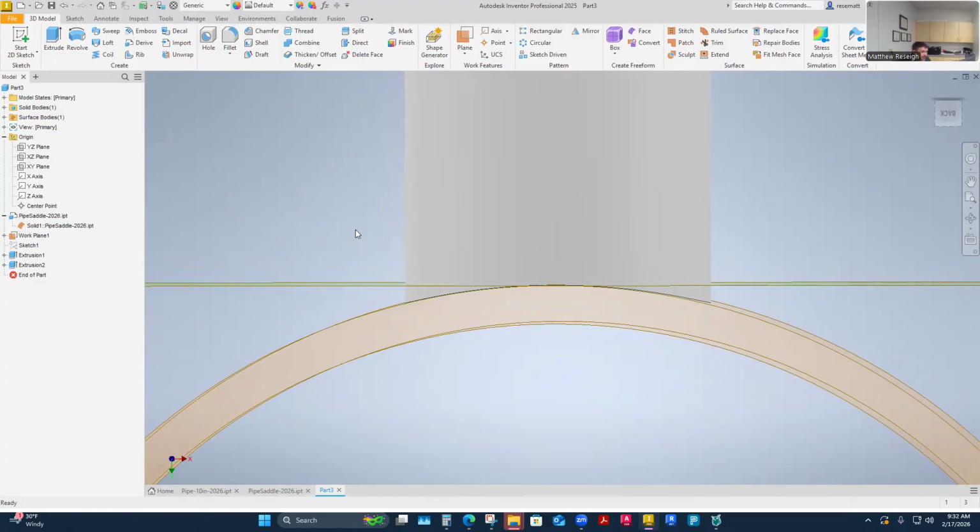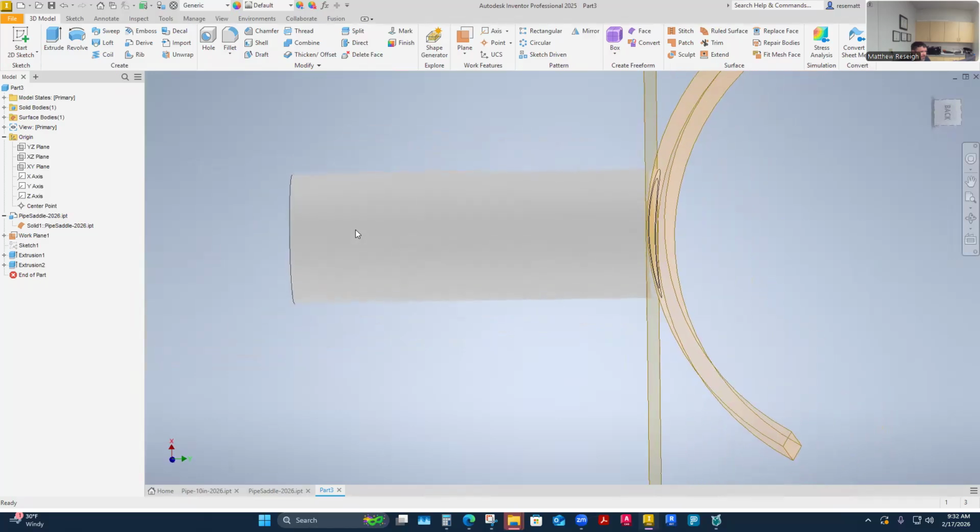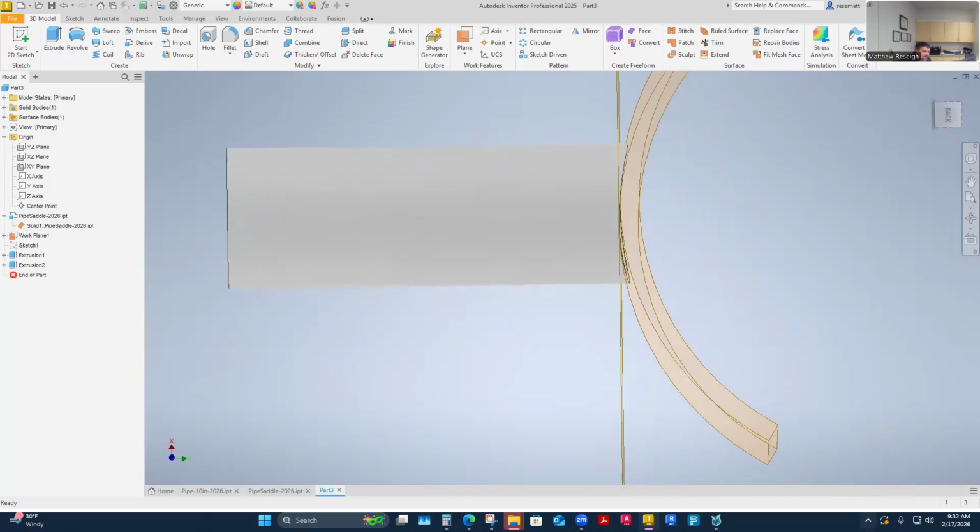But not all companies have those. They're really expensive. And so other companies might have a sander, like a belt sander. They can take this pipe in and bring it in nice and horizontal. I don't know if you guys have run belt sanders. The belt comes around kind of an end roll, but they can swap out the end rolls of those belt sanders for different diameters. And so people can actually hand sand a cope pattern in.